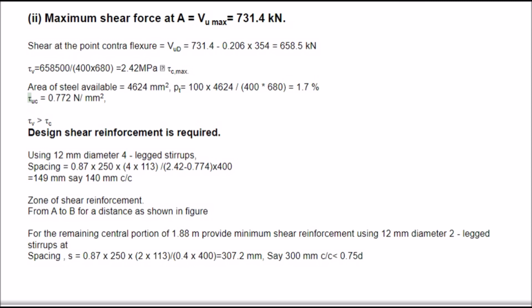Tau c equals 0.772 N/mm². Tau v greater than tau c. Design shear reinforcement is required.